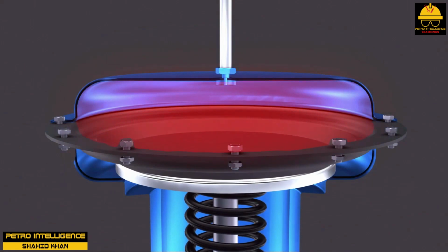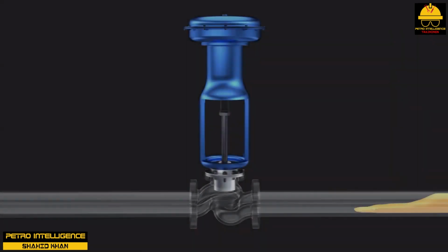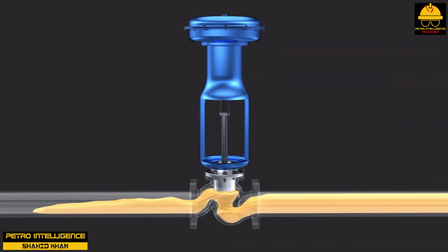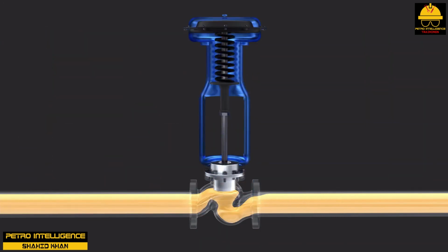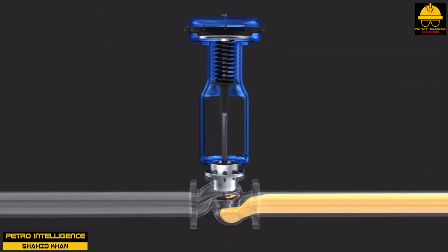The piston actuator uses an airtight cylinder and piston to move or position the stem. It is commonly found in use with automated gate valves or slide valves. It is used where a lot of stem travel is needed. Vane actuators direct air against paddles or vanes.